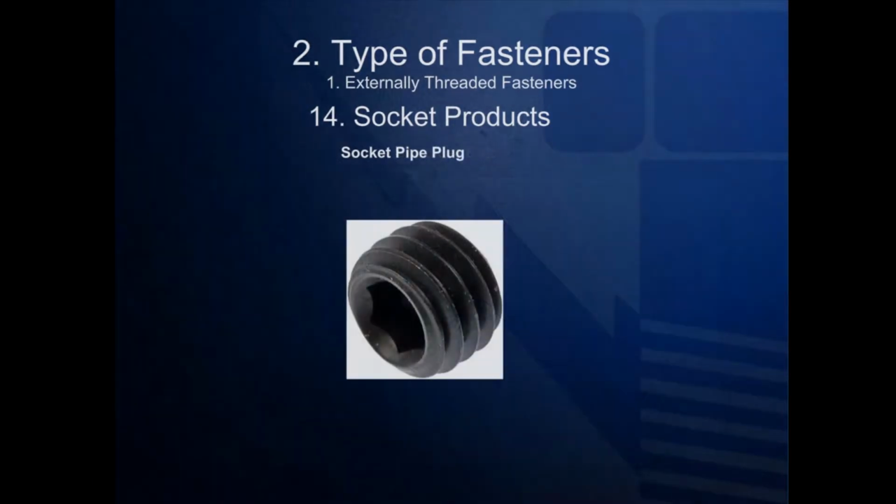I must admit, socket pipe plugs look almost identical to socket set screws, in which they are headless and have an indented hex for a drive. However, the difference is that socket pipe plugs are made with pipe thread. We'll talk more about this later, but National Pipe Thread, known as NPT, does not mate with any type of fastener. It's a different type of thread. Therefore, even if you tried, you wouldn't be able to put a half-inch nut onto a half-inch socket pipe plug.